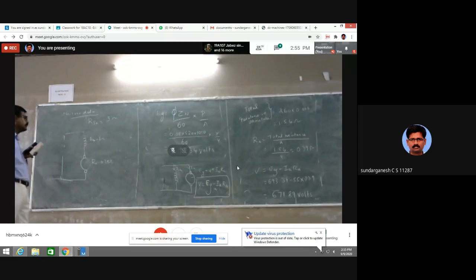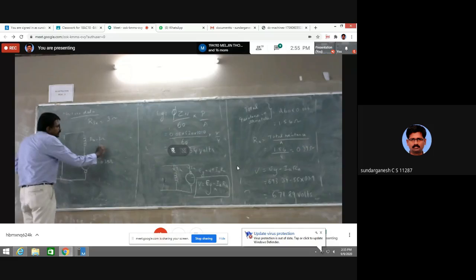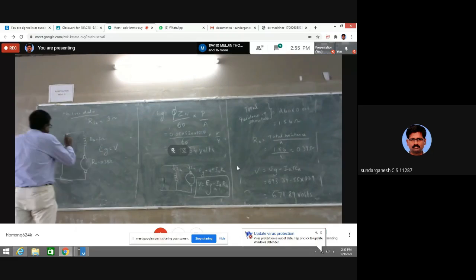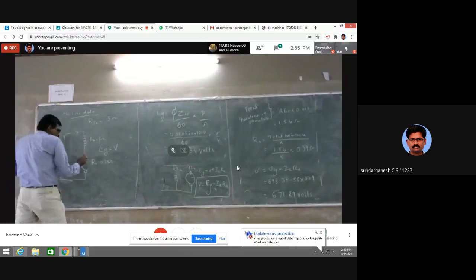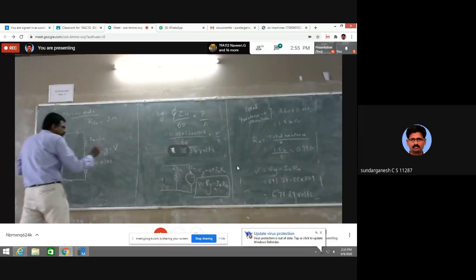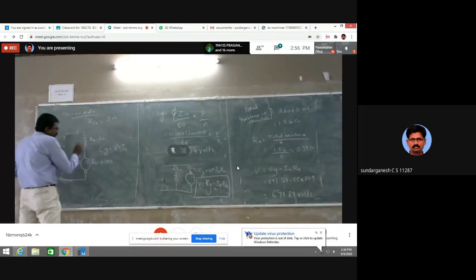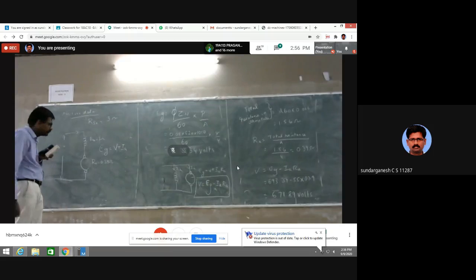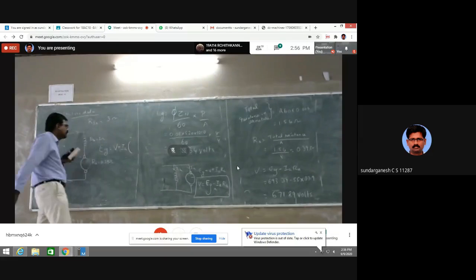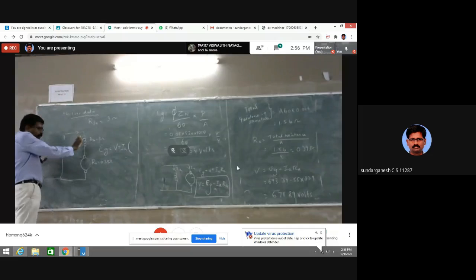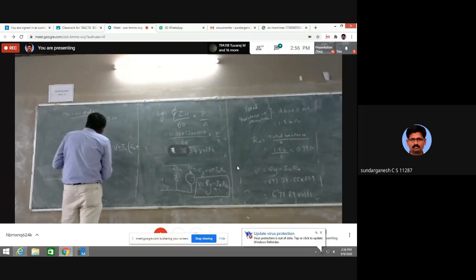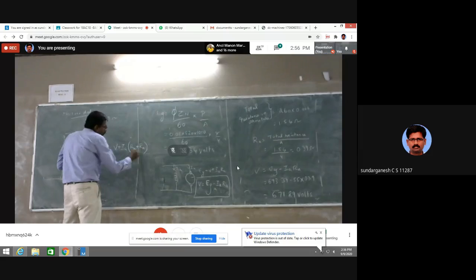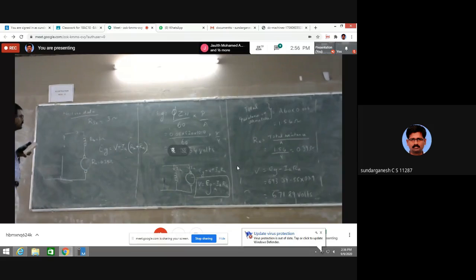Now we have to write the EG. In this case, EG equals V, this voltage. The same current flows through the series field and through IA, so I am taking it as IA itself, because IA and ISE are equal, since it is a series circuit. V plus IA, next, here there is some voltage drop. This voltage drop is IA RSE. This voltage drop is IA RA. So this is the equation for the series generator.